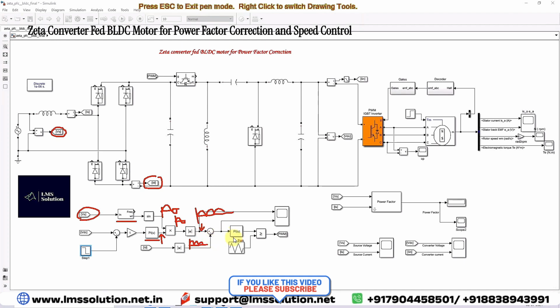Then it is processed via a PI controller. The PI controller will generate the duty cycle. The duty cycle is compared with the triangular wave. The triangular wave generates the pulse, the gating pulse for the IGBT. This pulse is going to alter the nature of the diode rectifier current.